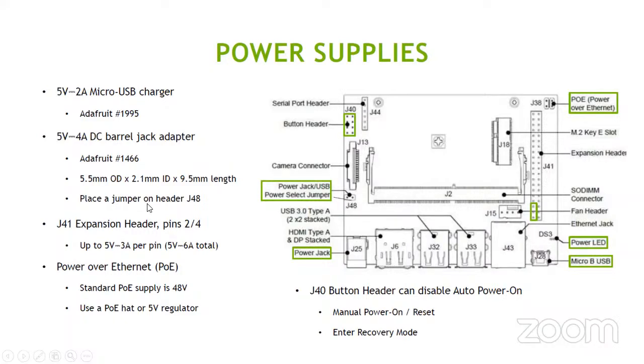You have to place a jumper on the header J48 to use the barrel jack. Otherwise, you cannot use the barrel jack. You cannot use the USB power, micro USB power.